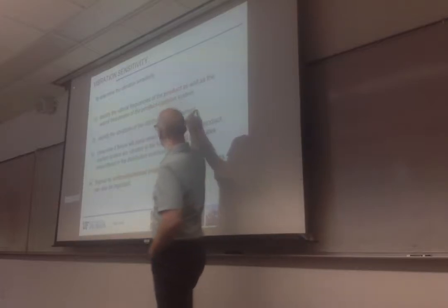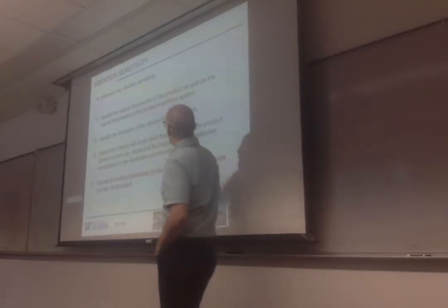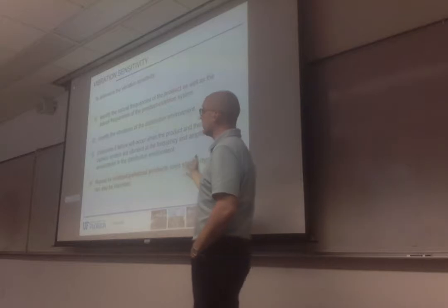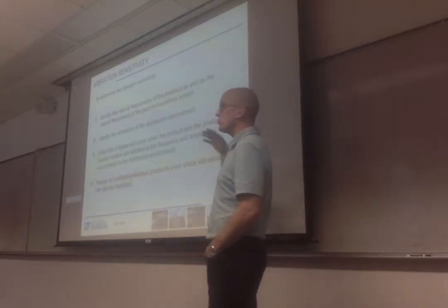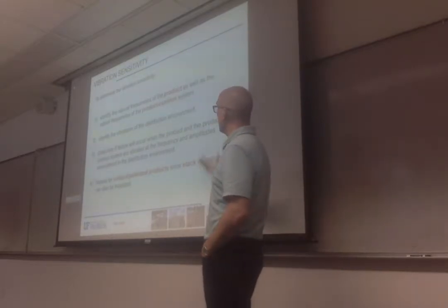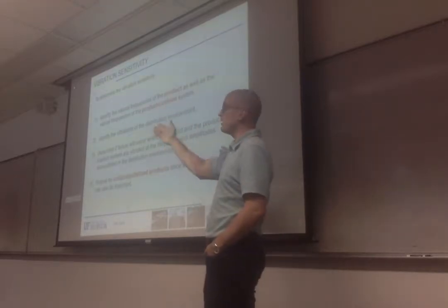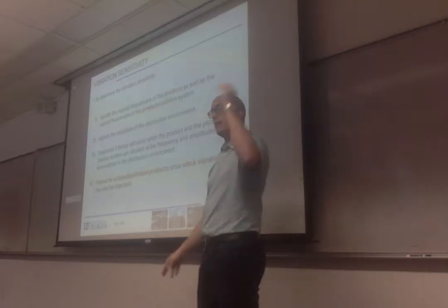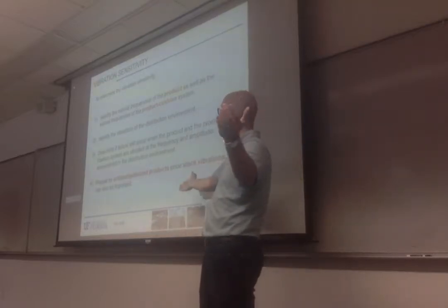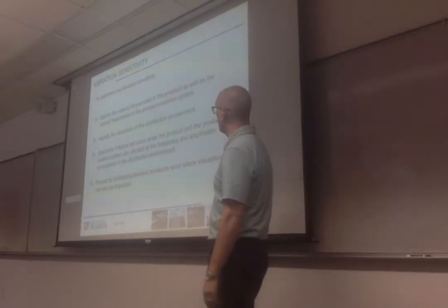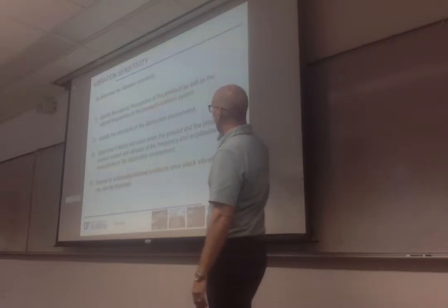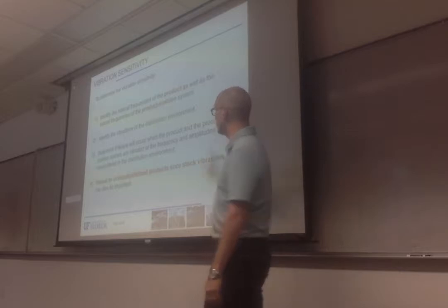This is typically pretty well known. Unless you use something pretty out of the ordinary, you should be able to go to standard procedures and identify what frequencies are dominant in air transport and road transportation. You can look at what ASTM is recommending, what ISTA is recommending, and this should be relatively known. Determine if failure will occur with the product and the product cushion system vibrated at the frequency and amplitude encountered in the distribution environment.